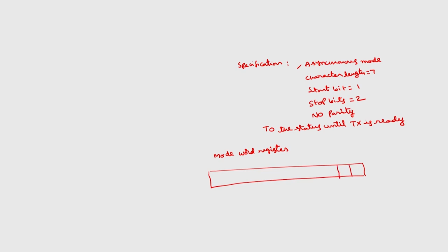Another specification is the clock frequency, which I want to be 153.6 kilohertz, and the baud rate is 9600 bits per second.